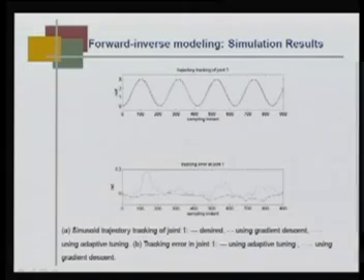This is the sinusoid trajectory that is being tracked by this robot manipulator. This is joint 1 angle, and you can easily see in the beginning there was some error, and that error died down as time progressed. And you can easily see there are two, this is the trajectory tracking, this is the tracking error at joint 1. So, this solid line is using the new update rule, whereas the dotted one is using gradient descent.